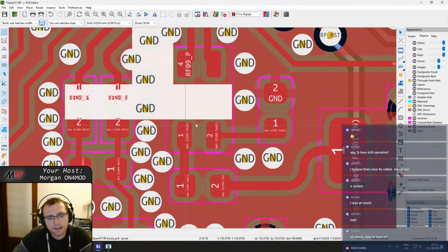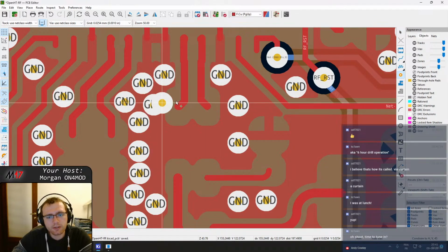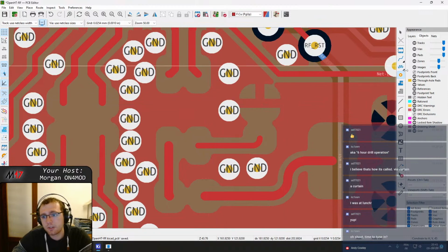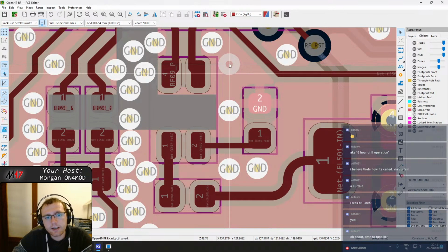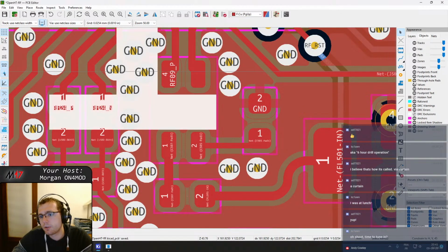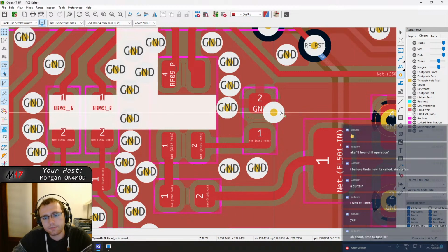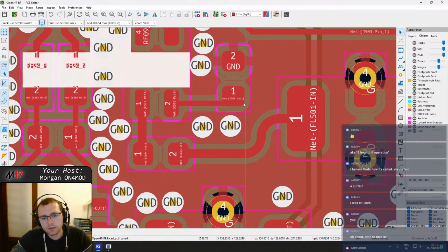But in the end, per via, it's cheaper to do the micro via thing. So sometimes they will just use micro vias because in the end it's cheaper anyway, even though the starting price is higher. So the fixed cost is higher, but the variable cost is lower. So at some point you have a break-even point, and you use micro vias, I guess. Well, you can't use micro via everywhere either.